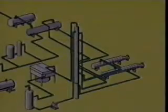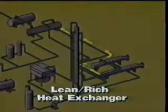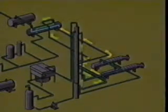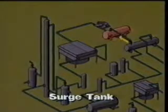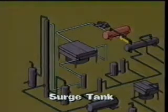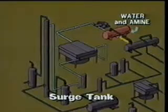The next step in the process is the lean-rich heat exchanger. From the reboiler, the hot lean amine flows through the heat exchanger and is cooled to a desired storage temperature by the rich amine solution on its way to the stripper column. The cooled lean amine from the heat exchanger is kept in a surge tank until it's pumped back to the top of the contactor column to begin the cycle again. Periodically, water and amine are added to the surge tank to make up for losses of these two liquids during the process.